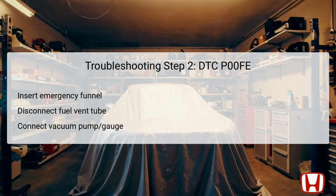In this second troubleshooting step, you will need to take specific actions to inspect the fuel tank system for blockages. Start by inserting the emergency fuel funnel into the fuel filler neck. This funnel is typically stored under the cargo floor lid for easy access. After securing the funnel, disconnect the fuel vent tube from the EVAP canister to allow for testing. Next, connect a vacuum pump or gauge, such as the Snap-on YA4000B, to the hose that leads from the fuel vent tube. By applying pressure to this hose, you can check if the pressure maintains itself properly.